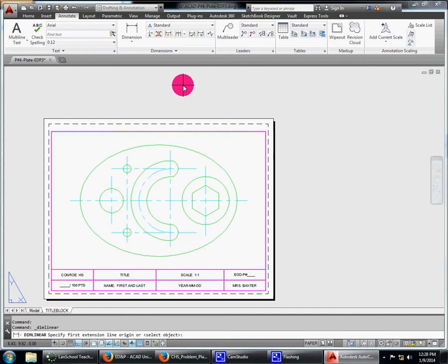different ones here. So we're going to start with first doing some linear dimensions. And I need to go from here to here. Move my mouse up. There we go. Very good. Hit the enter key so it continues it. And here, and here. Key, notice how I'm keeping it lined up. Enter key or the dimension tool again over and over again. Remember, enter key is great because it remembers the last command.